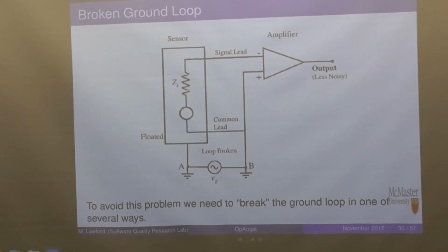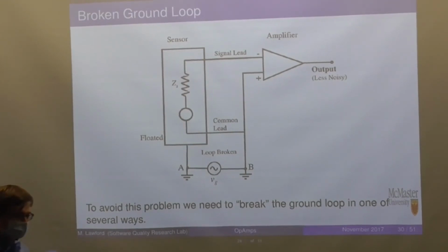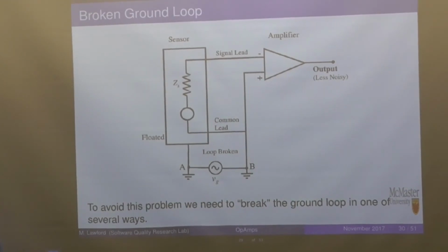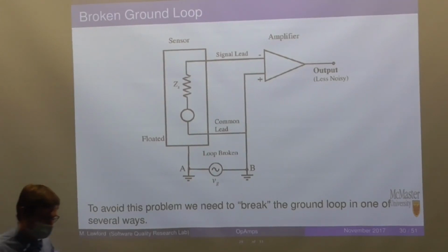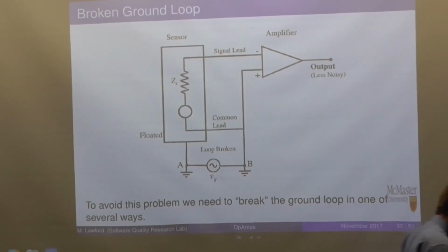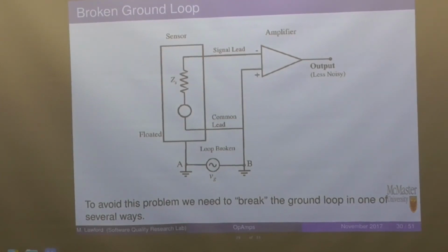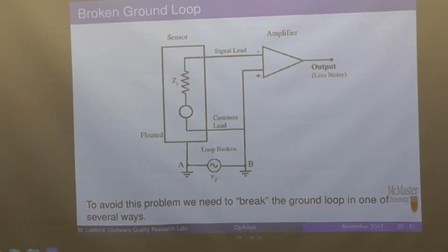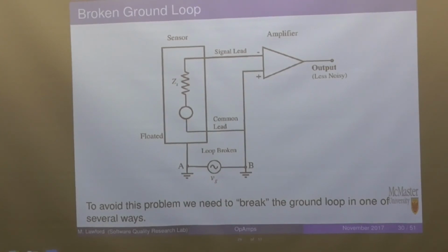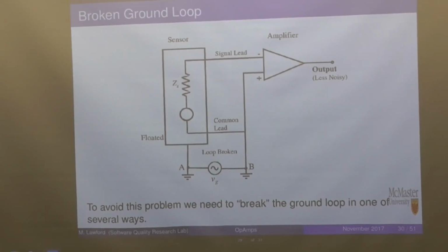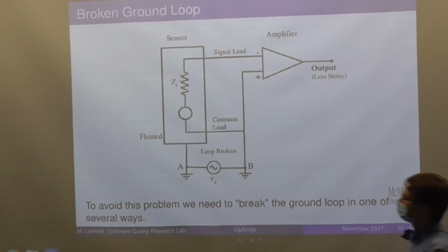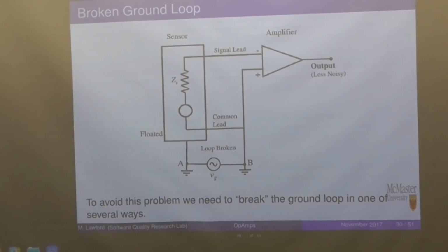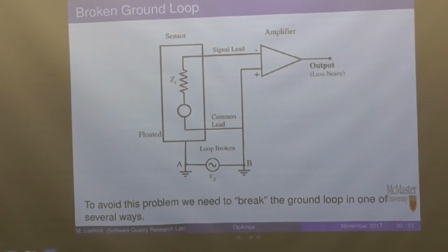And then you have to run it to a speaker. Or sometimes you can get the speaker in the amplifier, but they're different things. So, if the two of them are connected to different grounds, then you'll get like a buzzing, humming noise in your speaker. That's ground loop noise, right? So, this should help you avoid electric guitar problems.